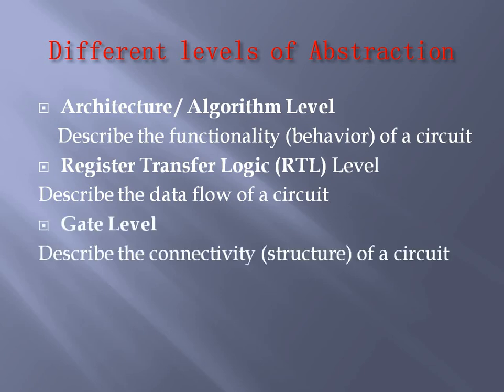And in the gate level, we describe the connectivity, in short the structure of a circuit. And next is the switch level, where MOSFETs are considered as switches, on switch and off switch, and if these MOSFETs are connected in one fashion, they build up your logic function. So if the hardware description language is described at the MOSFET level, that level is called the switch level.